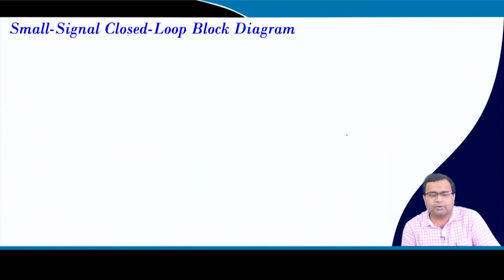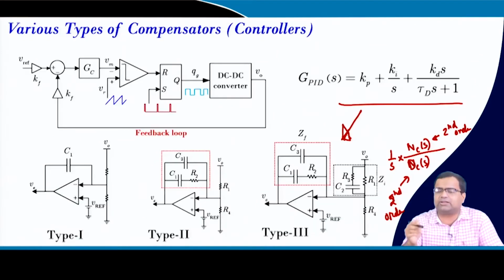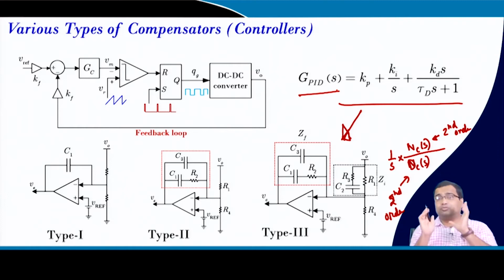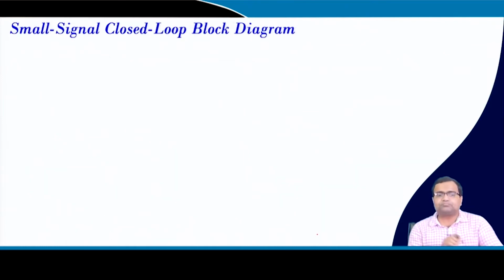And it will also show that the PID controller is of course not sufficient for a boost converter because there is a right half plane zero. So, you need to anticipate that effect using a type 3 compensator. Generally that is why the type 3 compensator is a very popular choice under voltage mode control.